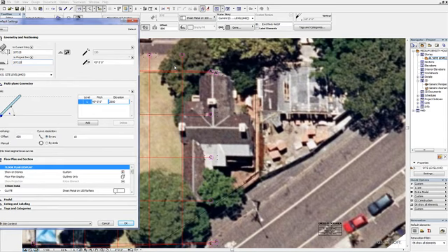Say it may block a lot of sunlight to existing windows, then we begin to have a reason to be concerned about the design that we're going to submit to council, because it may be rejected by council because it may not have more than, say, 2 hours of sunlight to this building, where the window is a window to, say, a living area.